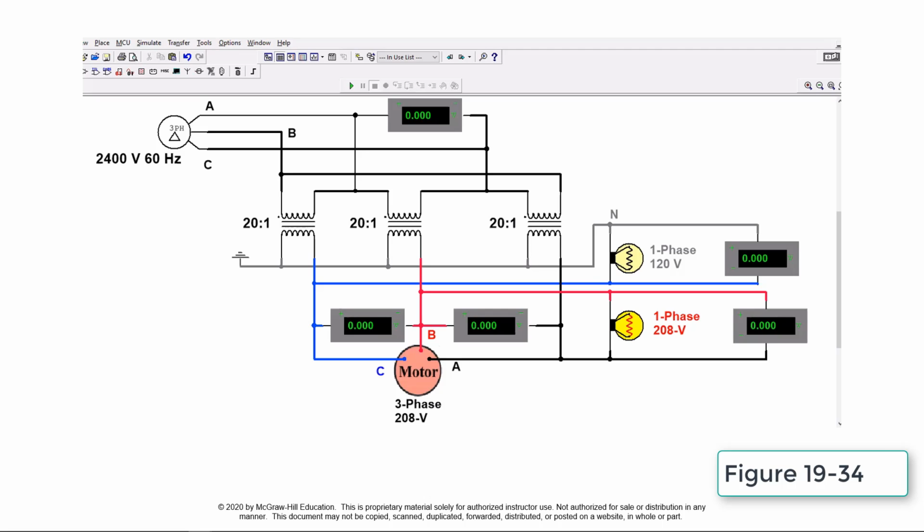The loads connected to a transformer should be connected so that the transformer is electrically balanced. Perfect electrical balance occurs when loads on a transformer are connected so that each phase of the transformer carries the same amount of current. Although perfect balance is rarely, if ever, achieved, it is something that you should strive for. The simulation is turned on to examine these characteristics.